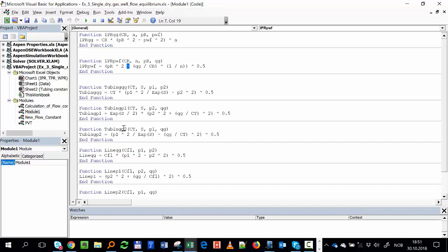I have P2 and I want to calculate P1. Counter current, right? So P1 is the available pressure, the required pressure at the tubing inlet. P2 is co-current, right? I'm going from the bottom hole all the way to the wellhead. And that's the available pressure at the wellhead. So which one of these two equations should I use for my case now?